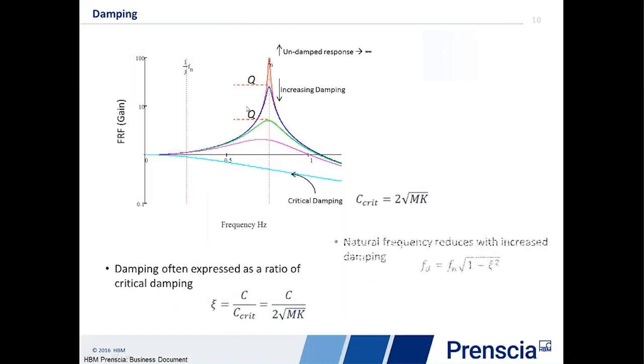So now we've discussed the frequency of a resonance, but as displayed before, a resonance shows a peak, and this peak may have different gain factors, the Q here. So for very lightly damped systems, like bells or crystal glass, you end up with a very, very low damping, so you end up with a very high peak, as if it was going to infinity. So you've got an infinite magnification at the resonant frequency.